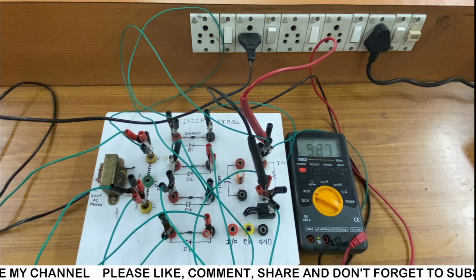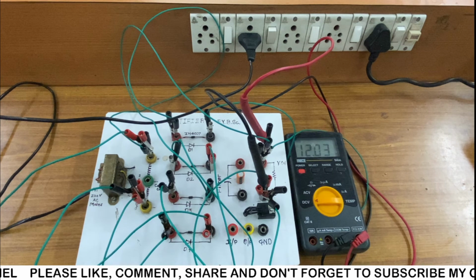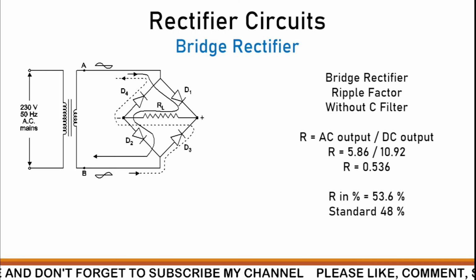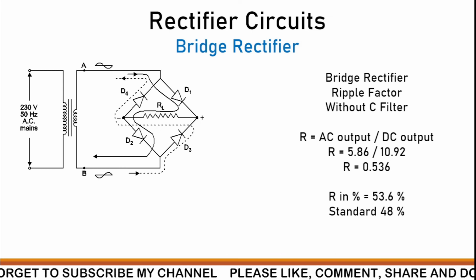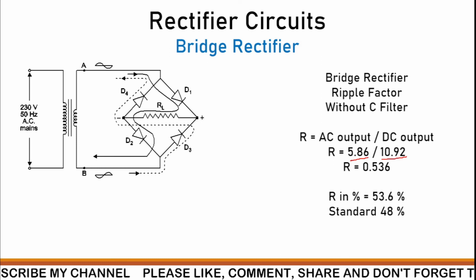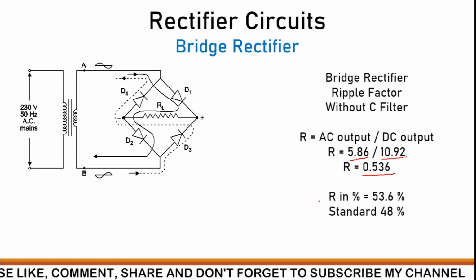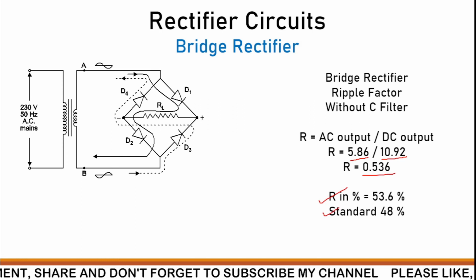So this is without C, 5.8786. And then I am going to measure the DC. This is 10.9293. The ripple factor without C filter for the bridge rectifier: AC output is 5.86 and DC output is 10.92. So in percentage it is 53.6, standard it is 48 percent.